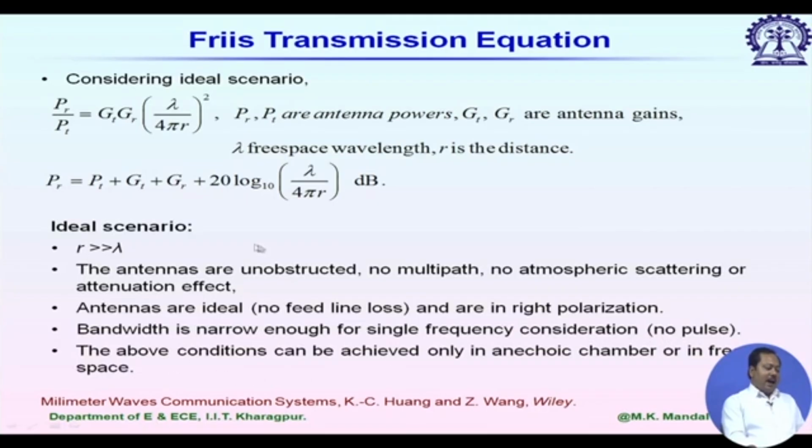Then the above conditions can be achieved only in free space or in an anechoic chamber. That is why any antenna measurement is done inside an anechoic chamber, where we do not have any external effect, we do not have any multipath effect, or any reflection from wall effect.